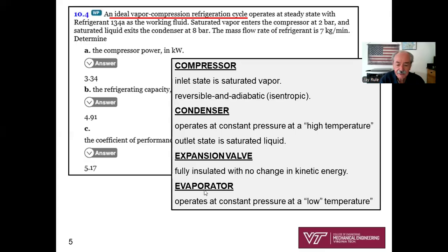And then we go into the evaporator with our phase change refrigerant. The evaporator is purely a heat exchanger operating at constant pressure, but it turns out that it's operating at a low temperature, and that's where you get your refrigeration effect. So I'm hoping that helps fill some blanks in.